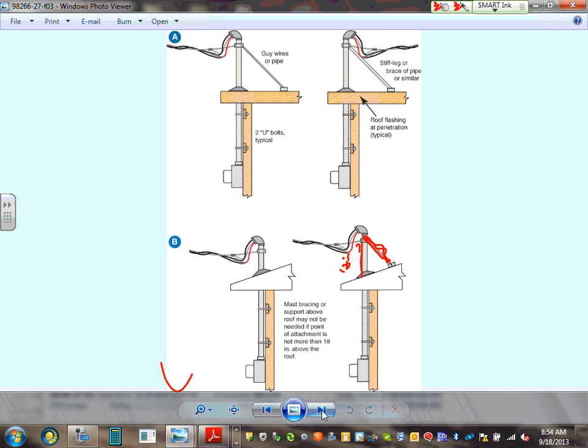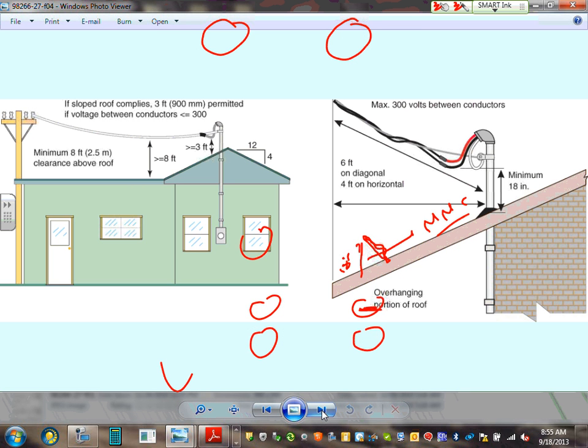There's a lot of hardware involved in it, guys. All the hardware involved in the connection, all the hardware involved in mounting this structure. This is typically rigid metal conduit that we use. When you mount a rigid metal conduit to a house, these are heavy equipment. Has anybody ever done that? And the anchoring mechanism, you have to be very careful what type of anchors you use. Otherwise, it's going to tip with wind and rain and all this good stuff. So just be aware of that as you design the system.